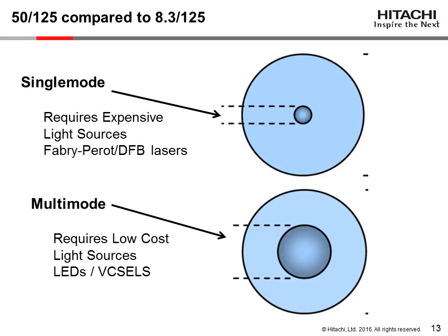The lasers associated with single-mode applications are very expensive and often require wavelength division multiplexing, the use of several lasers multiplexed into a single fiber, or several serial lasers running parallel over several fibers. In either case, single-mode multiplexing is very expensive, up to 10 times the cost of a multi-mode solution if it is used in short-distance applications.